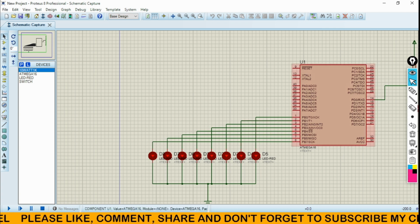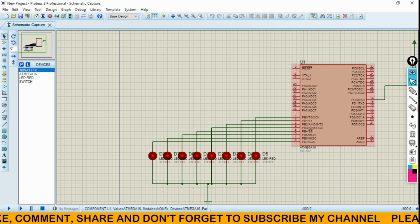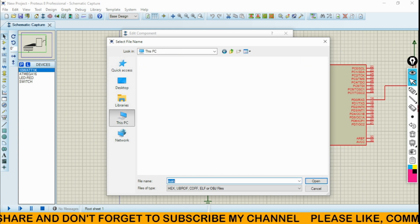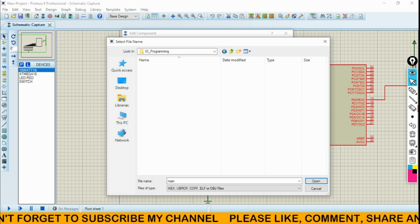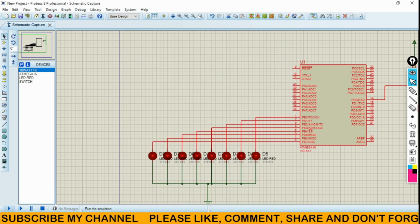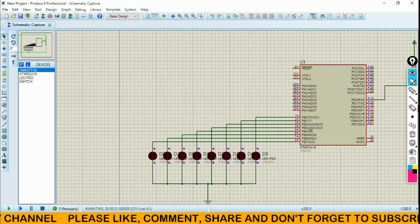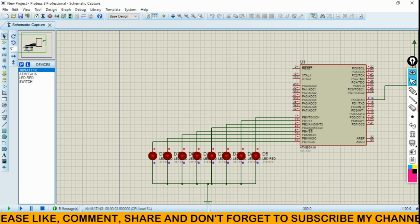As you can see here, I have connected the LEDs over here for port B. I'm going to insert the hex file that we have created to blink the port. We are programming the hex. Say OK. So you will see here the LEDs are blinking. For 1, the LEDs are all glowing, and for 0, the LEDs are off.